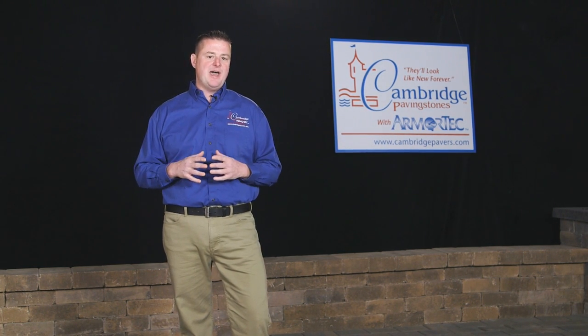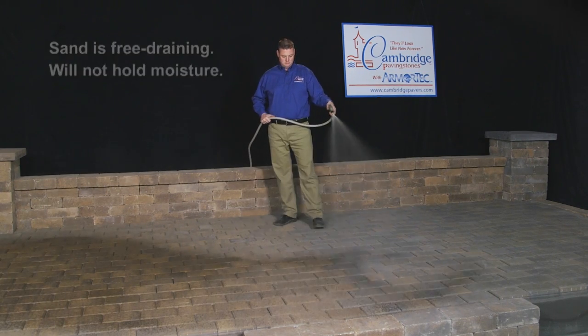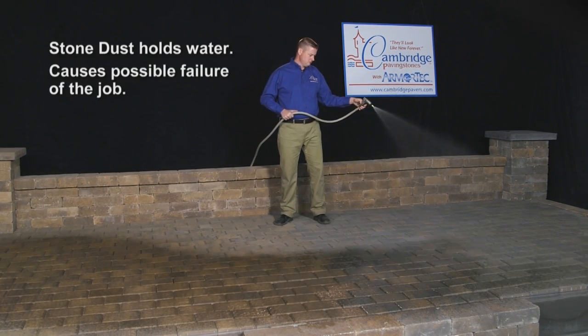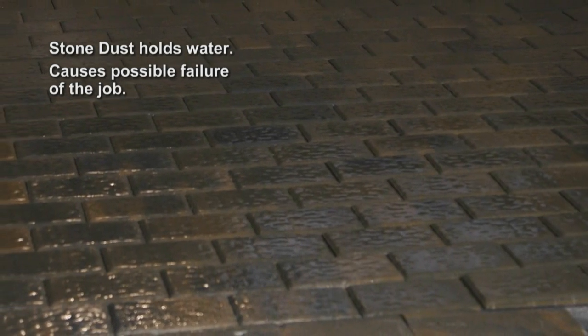The differences are also key in how each material acts under the paving stones in the installation. Sand is free draining and will not hold moisture. Stone dust, with its high percentage of fines, holds water and causes many issues and even failure of the job.